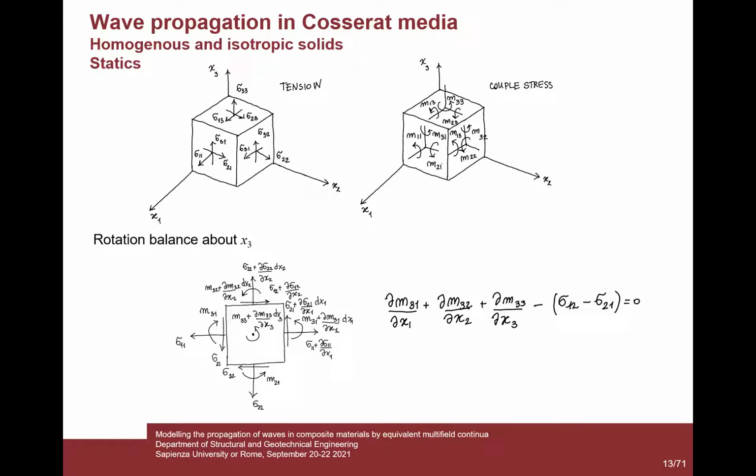I also wrote here some balance equations for the Cosserat medium, showing how it is possible to obtain the balance equations for an infinitesimal element. You see here, I have reported the tension stresses, which are the same as the Cauchy ones, besides the fact that in the Cosserat medium this tensor is non-symmetric. And here I have reported the couple stresses.